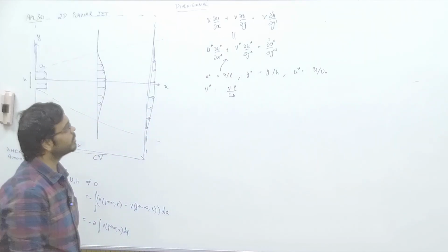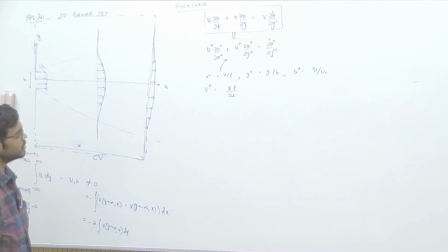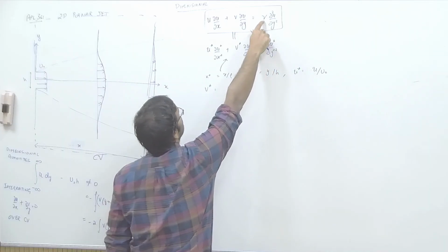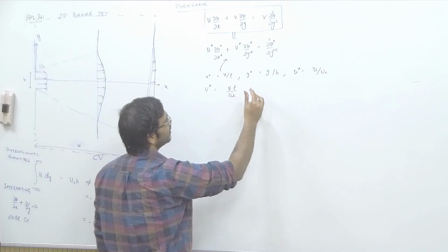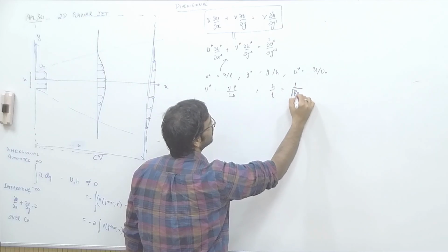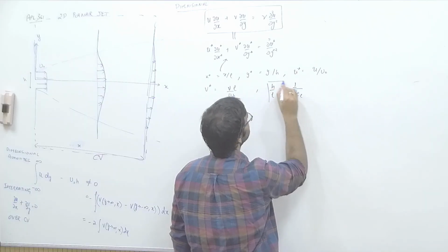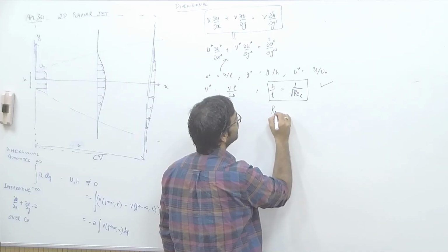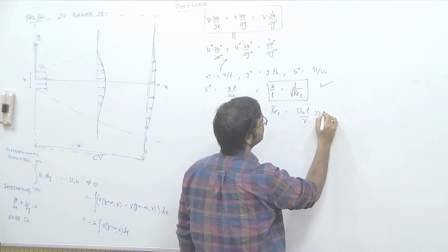Okay, so I am just trying to follow the procedure here. Now some of you may be asking, how will you get this, because you will get a Reynolds number and things like that, right? Because h and L, remember, we are doing it in the limit of h much less than L. Okay, we are doing it when this is upheld, and Re_L, which is u naught L over nu, is much greater than 1.